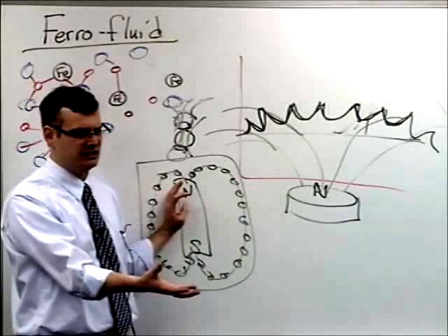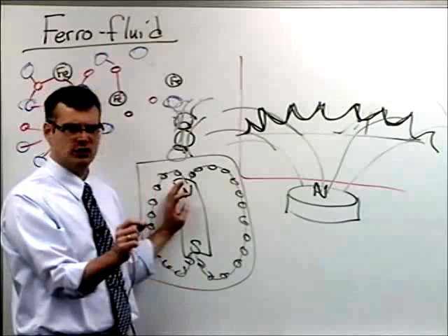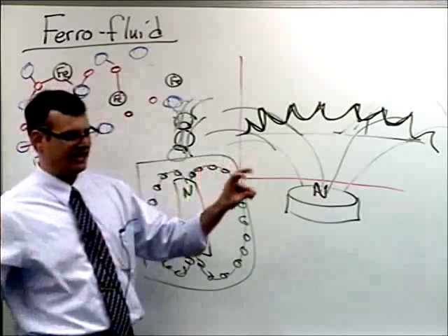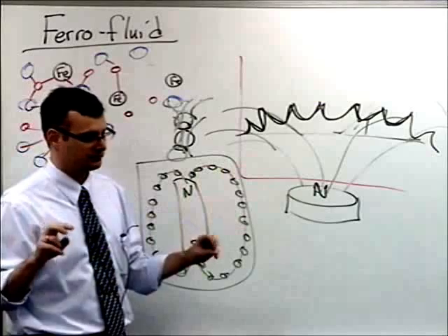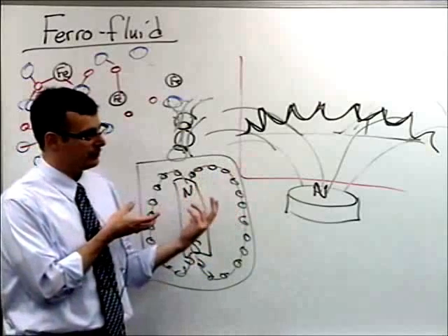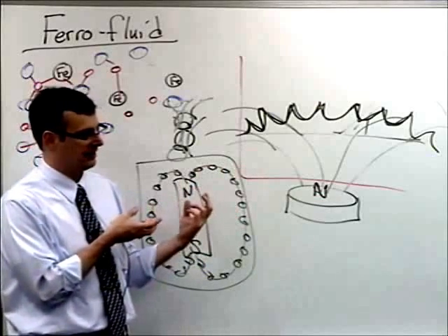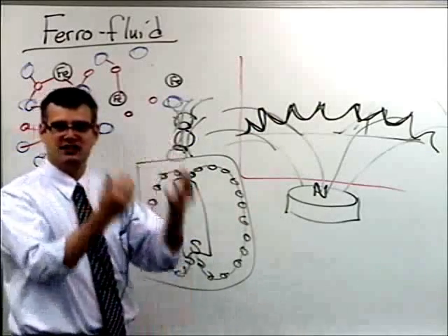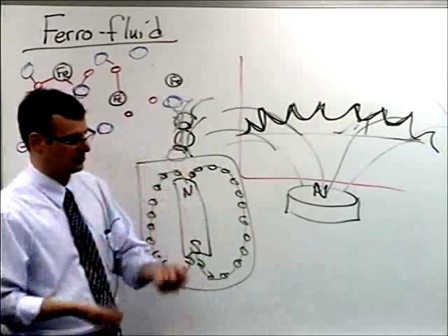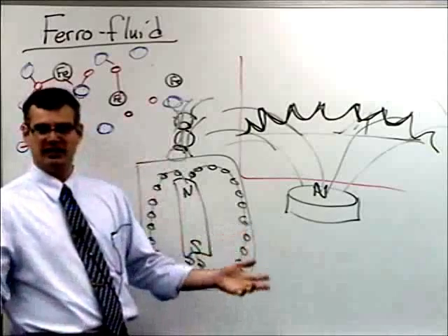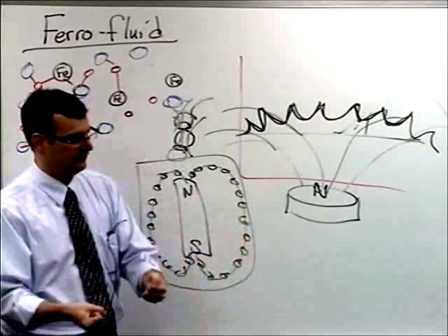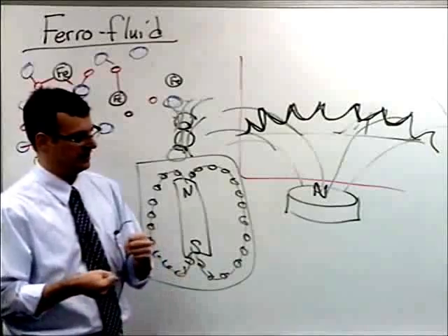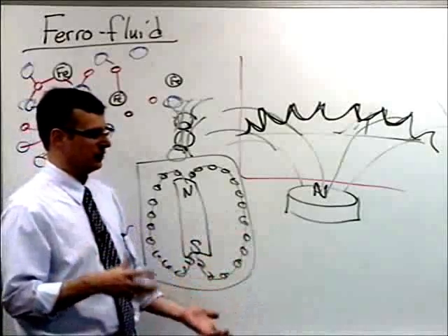And so has anybody seen those on real high-end cars? I think they've even advertised it in the commercials. Some fancy magnetic suspension system. Yeah, Mercedes. They're putting a fluid like this in the shock absorber, and by impressing a magnetic field, you're actually controlling the viscosity of the fluid in the shock absorber. So if you need a stiff shock, if you're going to high velocities, you want to get a good feel in the car, you impress the field and you stiffen it up. Then you relax it when you're going slower, or vice versa.